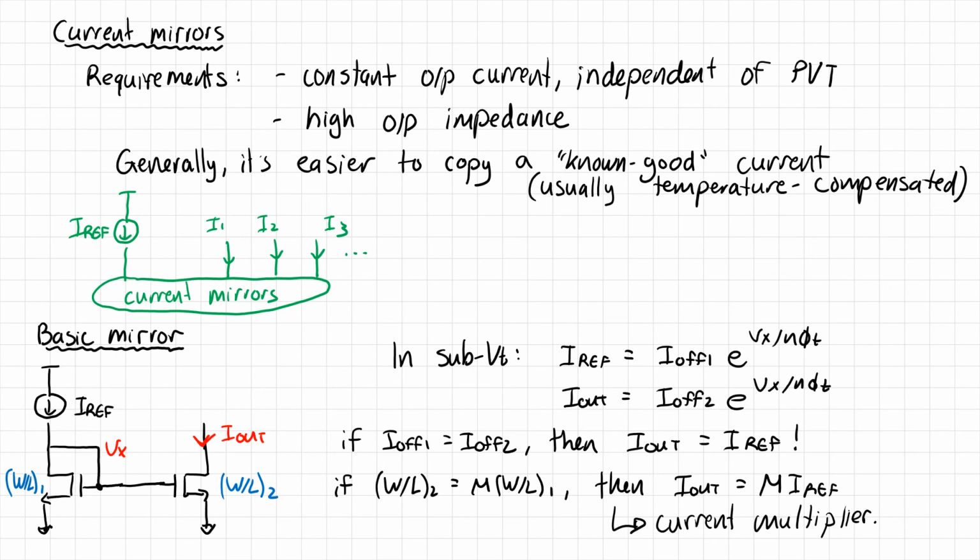So what we typically do is we will generate a single known good current source, Iref, and it'll usually be at fairly low current because it consumes power, and we ideally don't want to consume power in circuits that aren't giving us direct functionality like amplification. And then when we need to bias our amplifiers, we just build a mirror, and we usually mirror the current up. So let's say we need 100 nanoamps. Our reference generator, we'd maybe design it to be 10 nanoamps or 1 nanoamp, and we would multiply it up through this type of current mirror. We can also cascode the current mirrors to improve the output impedance and so on. So all of the good techniques that we know in analog design can be applied here as well.